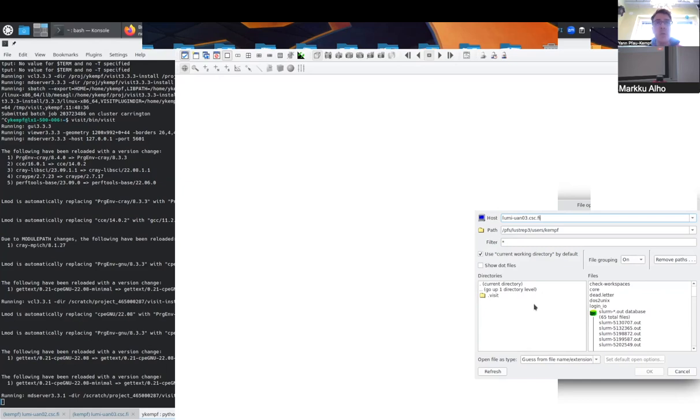One reason is that it's a bit more flexible because we can have these line by line, especially thinking of time varying. The boost library we use for parsing the config file reads a pair of option and value, so we'd need one line for each of the parameters: density, velocity x, velocity y, velocity z, and so on. Then we'd need to multiply that by the number of timelines we want. So it's a bit more convenient to have a separate file for these boundary conditions.